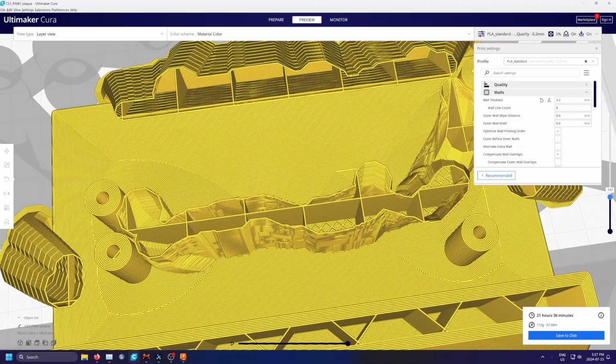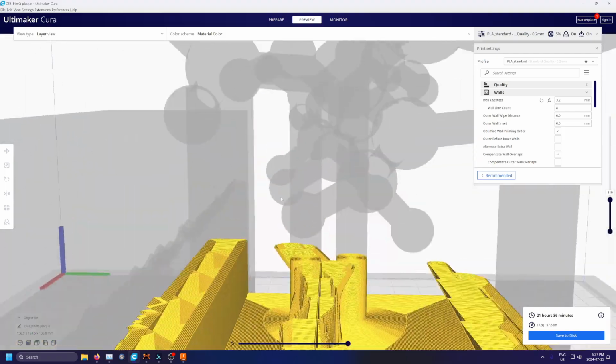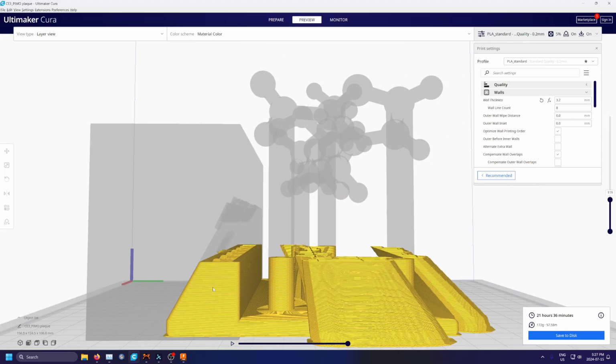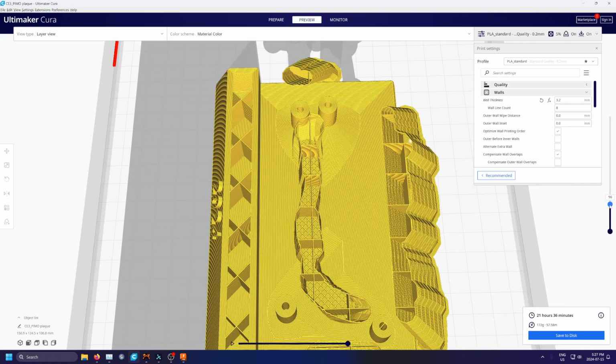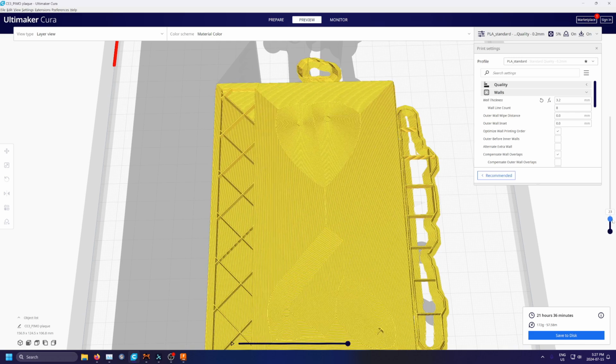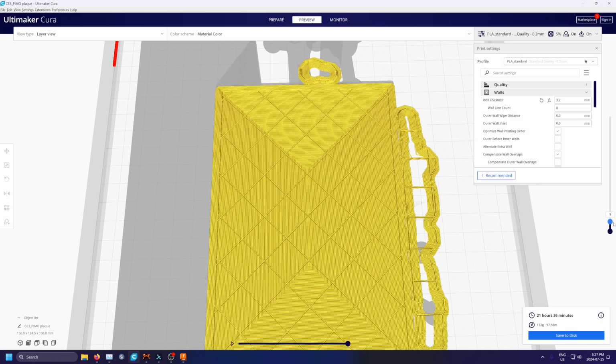Now, if we were to set the infill to 100%, this whole structure over here would be solid plastic. This bottom plate over here would be solid plastic. But all it really does is just waste tons and tons of plastic and would add considerably to build time. The only benefit is that it just feels a little bit heavier, and that weight adds to the perception of quality.